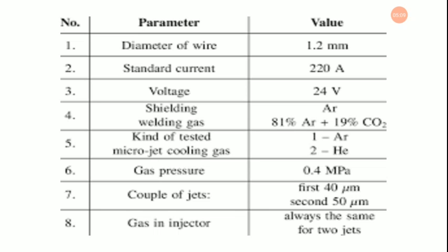These are greatly influenced by welding process parameters, welding speed, welding current, shielding gas flow rate, and gap distance. It is necessary to find an optimal GTAW process condition capable of producing desired weld quality. In the present study, optimization was performed in such a way that all the objectives should be fulfilled simultaneously. Such an optimization technique is called multi-response optimization.